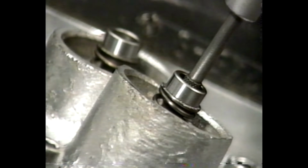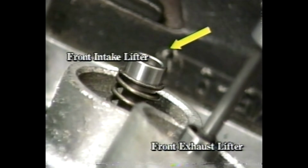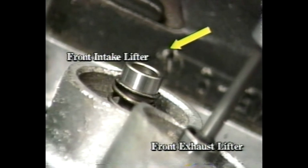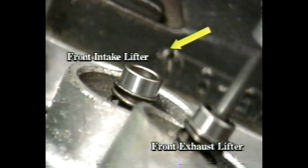It is very important that the stem of this dial indicator is seated at 90 degrees as well as being in the center of the lifter. To confirm that we are indeed on the compression stroke and approaching top dead center, the front intake lifter must be just beginning to fall, as shown here on this shovel head tappet block.